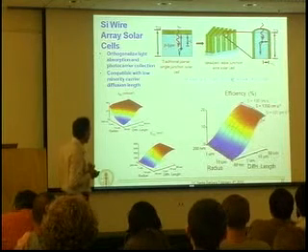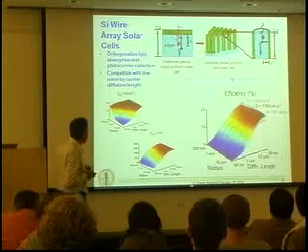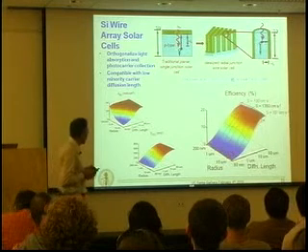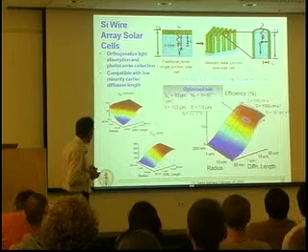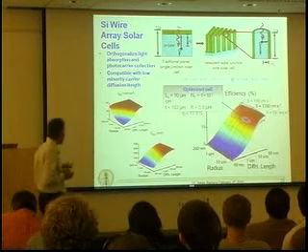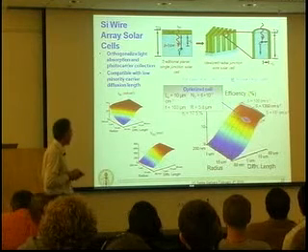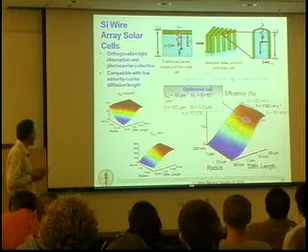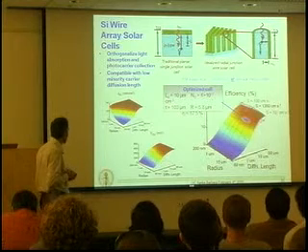It turned out in the end we made quite high quality silicon solar cells, and so we were no longer limited by this collection length, but we started to see some other advantages of this kind of cell. In fact, we've shown with some relatively comprehensive device modeling that you can get up into the 17 to 18% range with a cell using not very aggressive technology for fabrication of the cell and geometry and so forth.